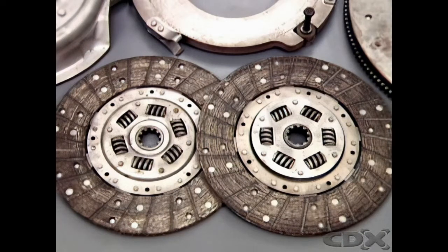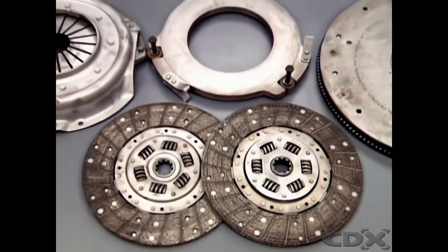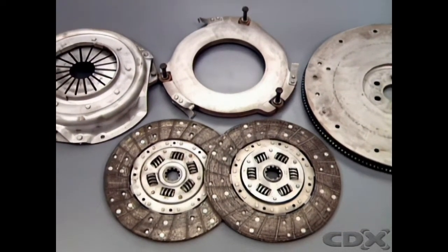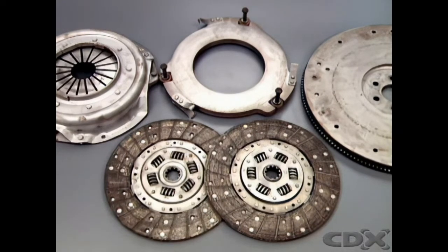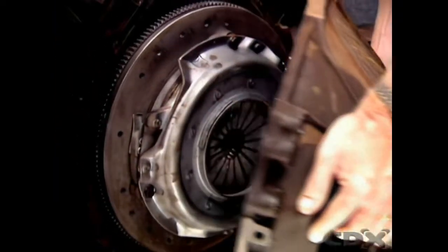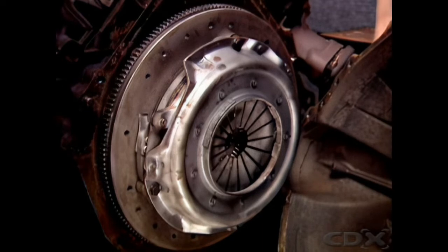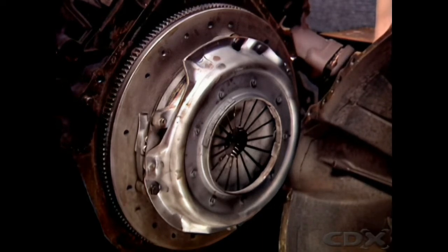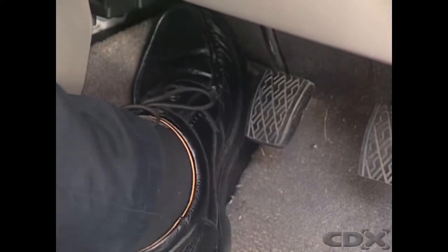Two or more clutch plates can be used to form a multiplate clutch, increasing the number of facings and torque capacity. They are useful where a reduction in diameter is advantageous or where increasing the spring strength is undesirable.